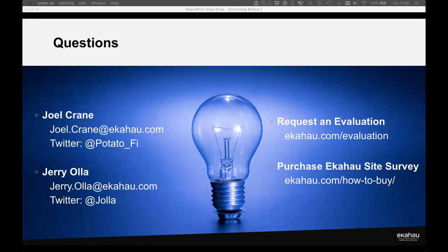My recommendation is that if you want to include a spectrum utilization value in your final reports when you're done with a survey, try to take the survey at a peak network time when people are using it. Sometimes that does mean you need to fight through crowds of people while doing the survey, which can be tricky. But just make sure that your customer or your manager or whoever you're giving this report to understands that that is a snapshot. That is a snapshot of what happened.